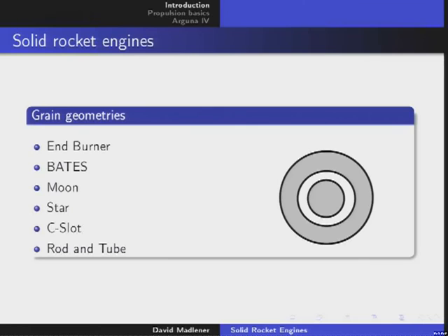But this is difficult because, of course, the rod in the middle can break, and if a fuel part breaks apart, of course it will go down in direction to the nozzle, and when the nozzle is reduced in diameter, so the throat is less open, then the pressure inside the chamber will rise very fast, and then the regression, that is the burning rate, will rise too, and then will produce more gas, and that can lead to a chamber burst. So this is a difficult design.